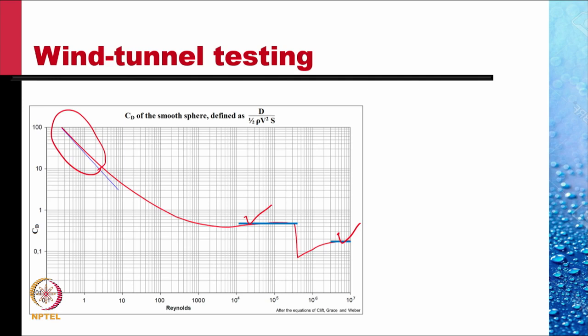Since most of the flows in aerodynamics are high Reynolds number flows in which we are interested, postulating that the drag coefficient is independent of Reynolds number on the aerodynamic body is an often made assumption. So we use the relaxation that viscous effects could be neglected and the drag force is governed largely by pressure forces and inertia forces.